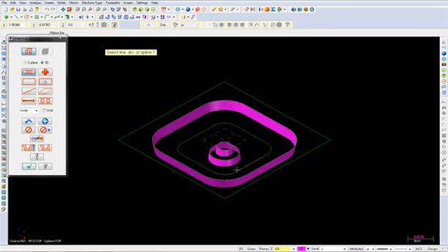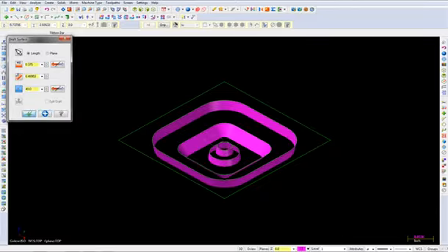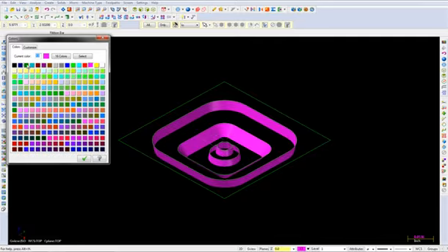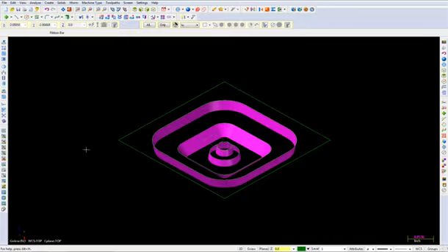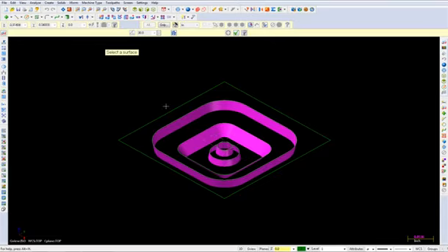Select the Apply button, chain this rectangle here. Choose the OK button. Leave the length set to 0.375 and change the angle to 40 degrees. Ensure that it's also created downwards. Select the OK button to exit this dialog box. Left click on Color here and change the main color to green number 2. Select the OK button. Choose the command Create Curve, Curve on one edge.